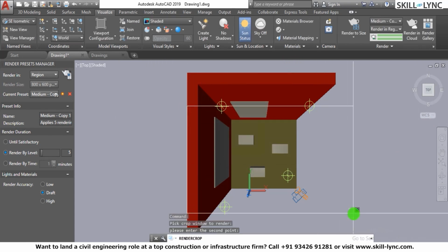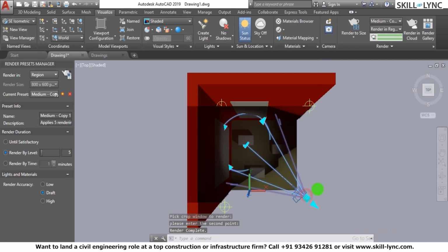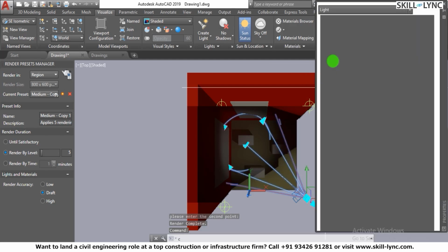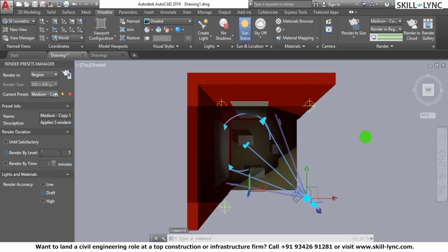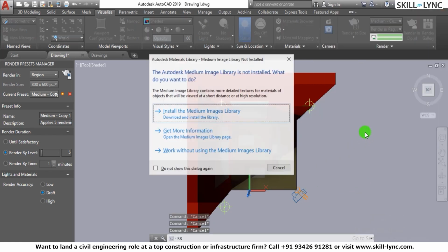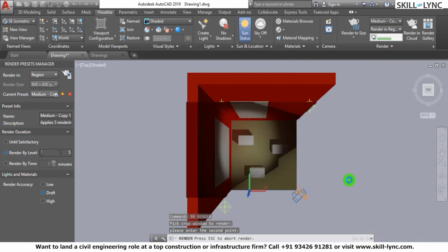So I'm just putting this. So the area for the light has increased. So I'm just increasing the intensity. Let's say here I go to the properties and increase the intensity, let's say 5 times to see a brighter light. So you can see the rendering option now. So lighting is something that you have to fix, and then the texturing, now things are better.